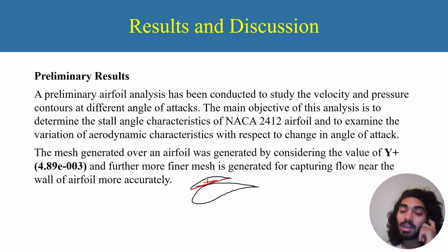For boundary layer kind of problems, we consider the y plus value. Why? Because the whole phenomenon occurs within the boundary layer, so that's why this height is much more important. If we don't consider the y plus value, and you give the first layer wrongly, you can't get the results. You give the first boundary layer of the mesh, and in between these layers you give 5 layers, then you can capture it. So that's why considering this value is very much required.